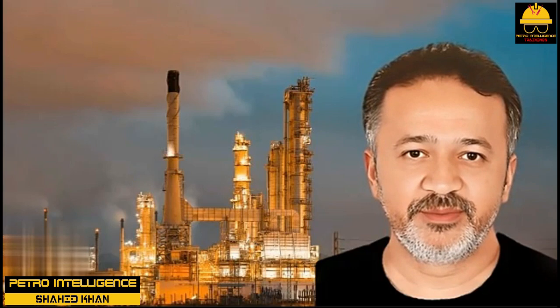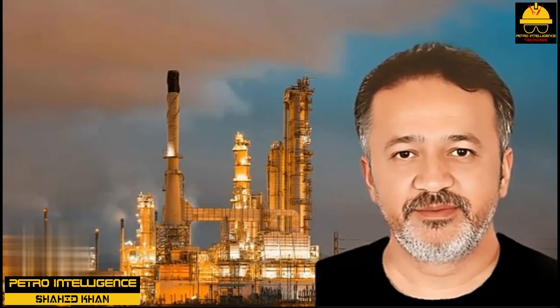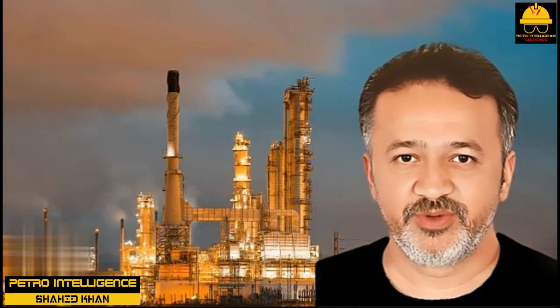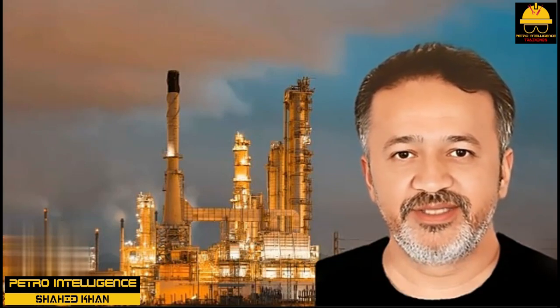To answer this fundamental question, we should realize that reducing the tower pressure would also reduce both the tower top temperature and the tower bottom temperature. Therefore, the change in these temperatures, by themselves, is not particularly informative. But if we look at the difference between the bottom and top temperatures, this difference is an excellent indication of fractionation efficiency. The bigger this temperature difference, the better the split.